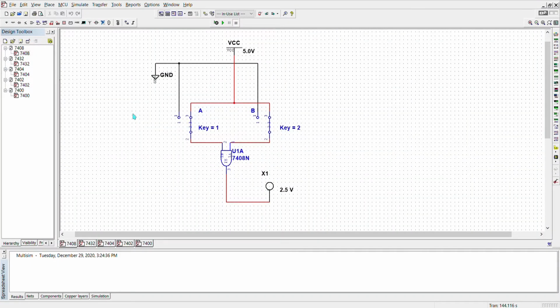To run the circuit, firstly we need to press the play and run button, and as in the lab sheet, firstly they need the input for A and B to be 0. So with input A and B 0, the output is also 0, as the probe is not lit up. Then the B input is 1, the output is 0. The input of A is 1, the output is 0. And lastly, with the input of A and B 1, the output is 1.